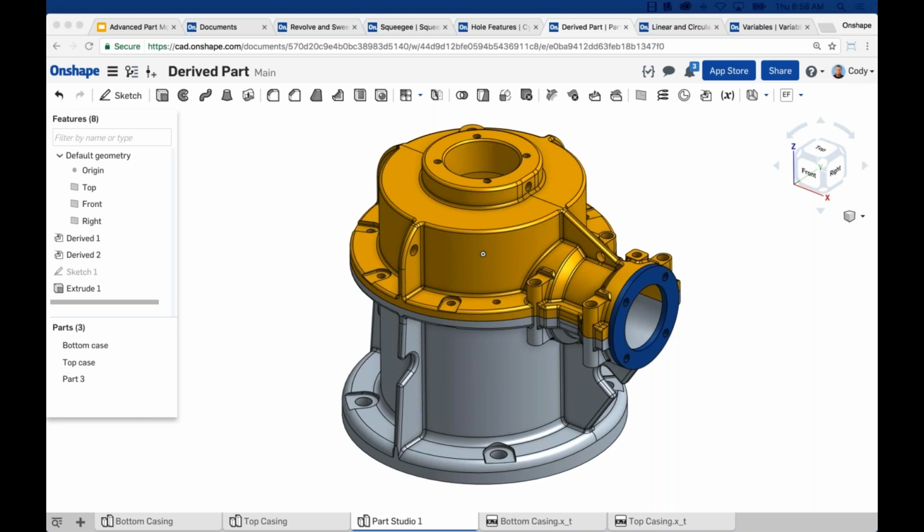In derived part, what if the origins of the part do not line up nicely like in your example? And that's a very good question. I would recommend using the transform with mate connectors command. I don't have time to get into it now, but I have done a webinar on this topic. So definitely do a search for the derived feature. I walk through the workflow.